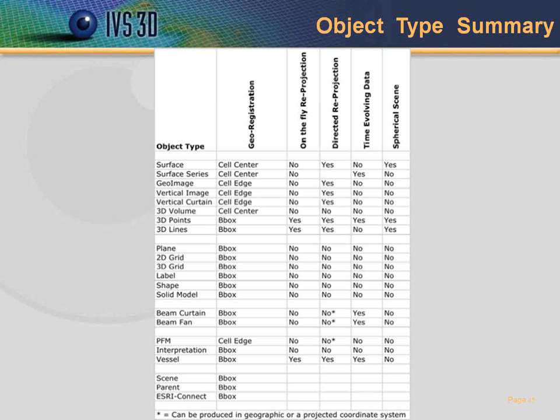It was just about surfaces, scalars versus DTMs, and the question was, how do you get scalar data in? The answer is you import scalar data. If you have it as, say, an ASCII XYZ file, you would import scalar as a grid, and then in the last screen it asks you if you want to create a scalar SD or a surface SD. When you create a scalar SD, you'll create the kind of flat grid that Mark showed in the demonstration. Do you have anything else to add on that? Nope, that's correct. That's the way they're normally produced.